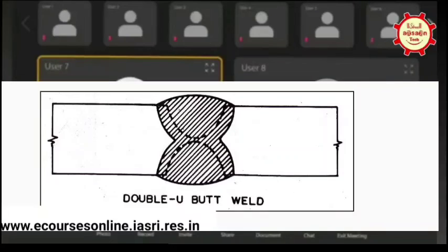Actually, it's used for higher thickness, and in our case, the planner and the welding engineer decided together with the design engineer. Is there any reference in the code? Somebody was saying there is a reference in the code. It might be in section 9, but in section 8, I don't think there is. Also, they do this to reduce the material and consumable consumption. Yeah, one reference is given in the code. That is, we can use single V up to 16 mm. That is the only reference I find.